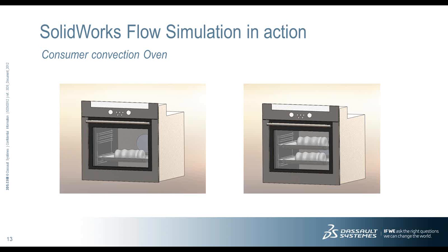A wall oven uses electric heating elements to generate heat over a range of temperatures. So the heat is convected into the surrounding air, which then moves to heat the cooking volume. A fan oven employs a fan to speed up the warm-up time and achieve a more uniform temperature distribution. So today, for this example, we will look at how to set up the CFD analysis in SolidWorks Flow Simulation, and more importantly, how to access the results for design insight for lots of design scenarios.